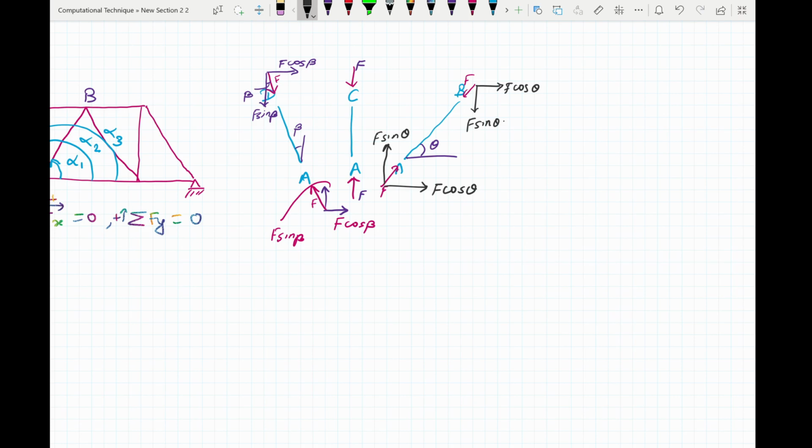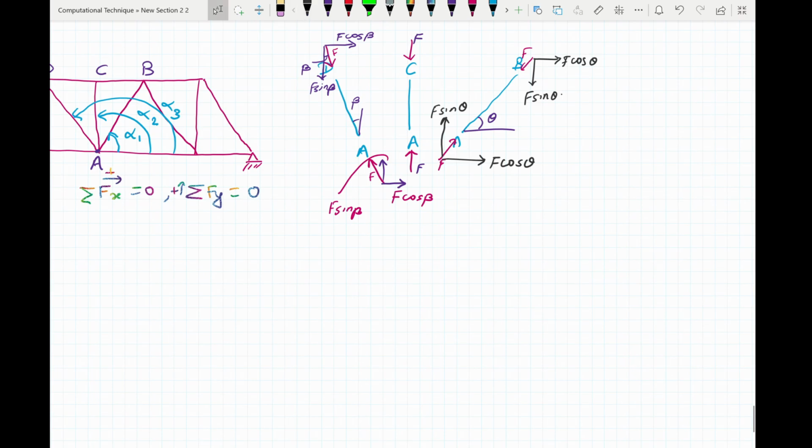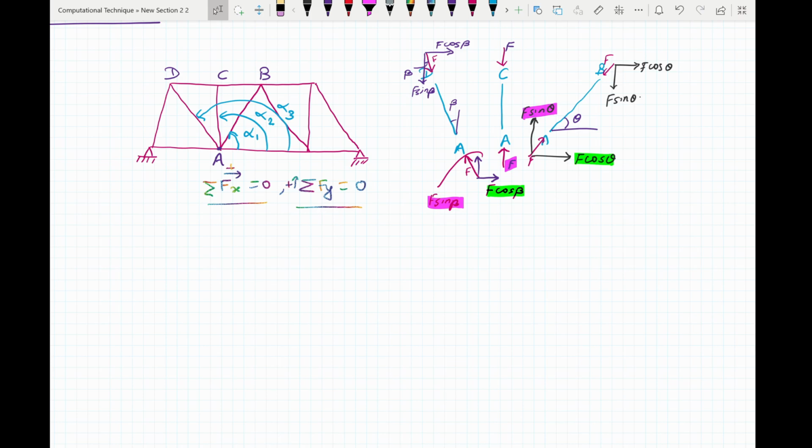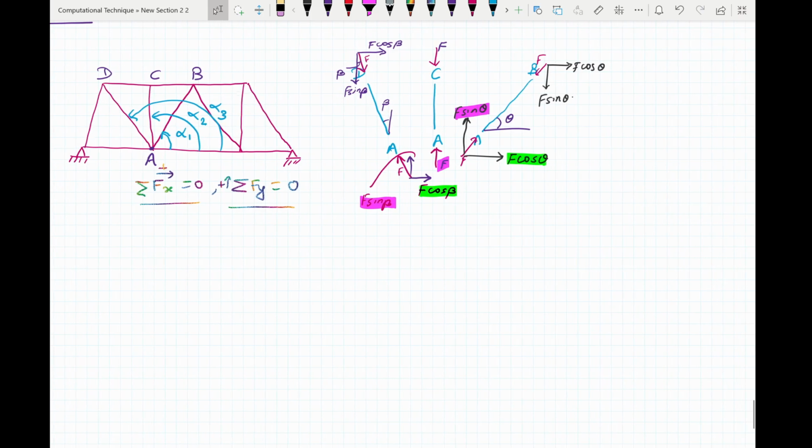Therefore, for each of these elements, we can obtain our horizontal forces and vertical forces. If we look into the global system, only then we can add these up to apply the equilibrium. Therefore, we have to formulate a stiffness matrix which takes care of these orientations.